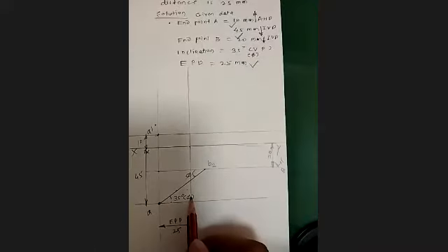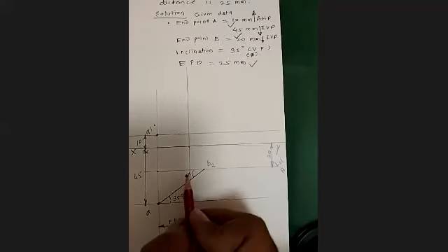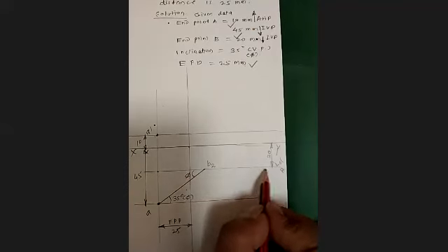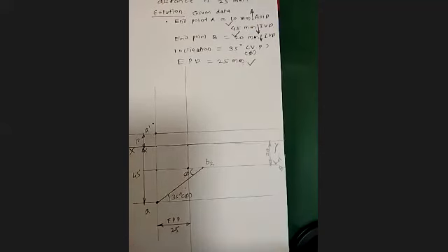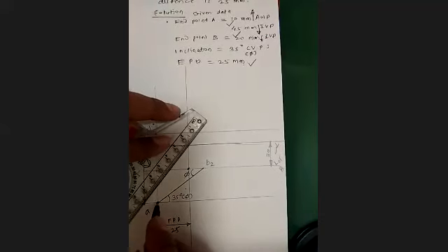This is the true length line. This is where the angle is phi. Phi end point is always B2. See, now you are going to get here, wherever the locus of point B and end projected distance intersect with each other, and this is going to give you the top view, or you can say the plan.